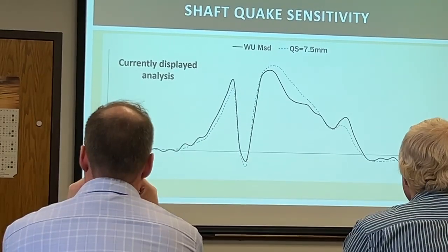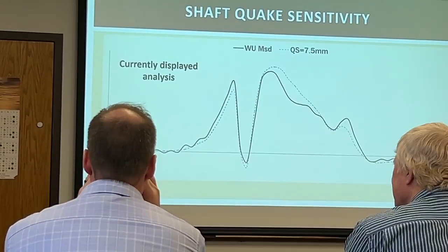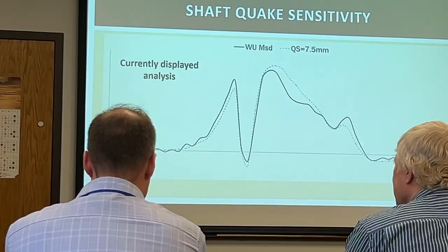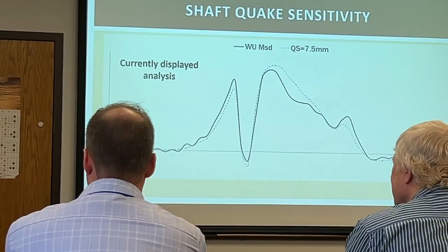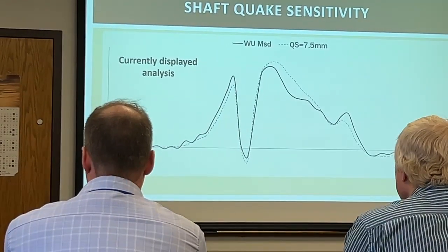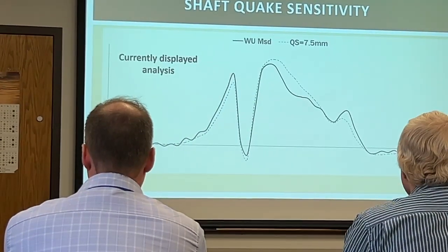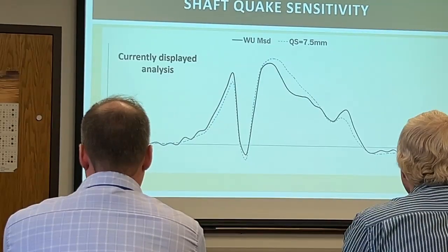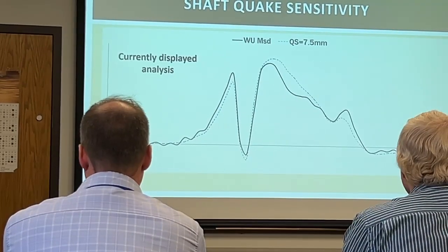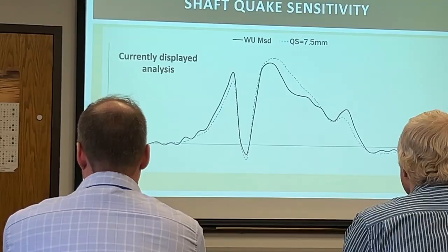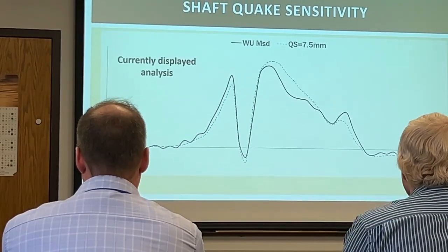That is, if we do a direct shear test, typically we've mobilized most of our resistance, or we've reached a peak after 1/10 of an inch or less. And depending on the soil, we can quibble about that on a 5/100ths of an inch kind of basis, but generally speaking, that's what we're looking at.